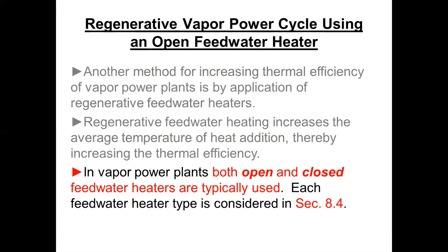The steam condenses into the water as it strips off. It falls down to the bottom and goes out. A deaerator has to have a small vent, so a little bit of steam is vented, and that pulls out the non-condensable gases, which exit up through the top of the deaerator. We can look at those cycles in a little bit and see if we can trace that out.